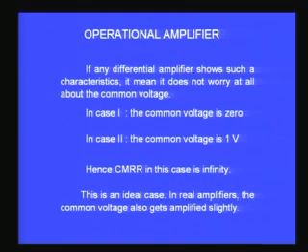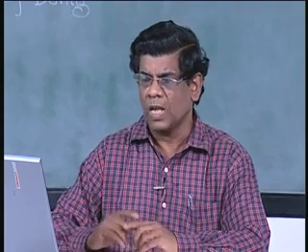If an amplifier can show such characteristics, we call that amplifier an excellent amplifier, an ideal amplifier, and the CMRR in this case can be infinity. It is completely able to reject all the common voltages, it is only amplifying the difference in the two signals. But I already mentioned to you, in reality you would find it is very difficult to get such high value CMRR. You can with great difficulty get 90 dB or 100 dB, etc. Therefore,